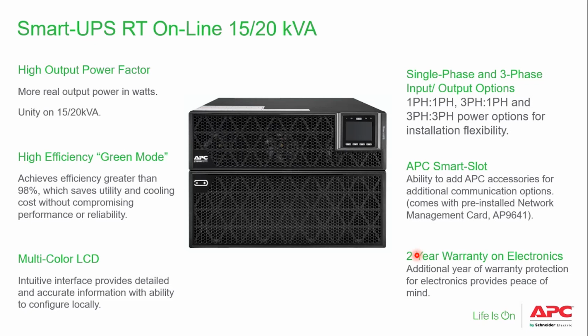So suppose any customer is willing to connect a very sensitive device, such as for defense purposes, or any very costly server of a bank or of the Indian Army or Indian Air Force, then they will be very much secure that the server should not be down. So these are for very high applications. Four UPSs can be connected on a single battery bank, so that if one or two UPS fail, the complete load will be shifted to the good working UPS.